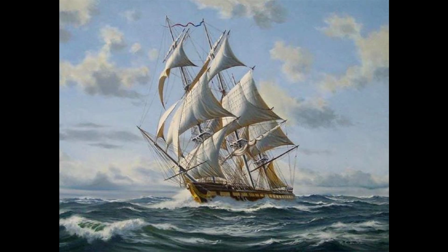So I want you to try and construct that whole bottom of the boat using a loft. I want you to construct the masts, and the masts are tapered. So give that a go with lofting as well. Bigger circle at the bottom, smaller circle at the top. And you've got some other bits and pieces on there. Maybe you could try out a sweep for one of the crow's nests, and then I want you to try out some lofting for some sails. Okay, and sails are really easy. They're just one curve following a rail.